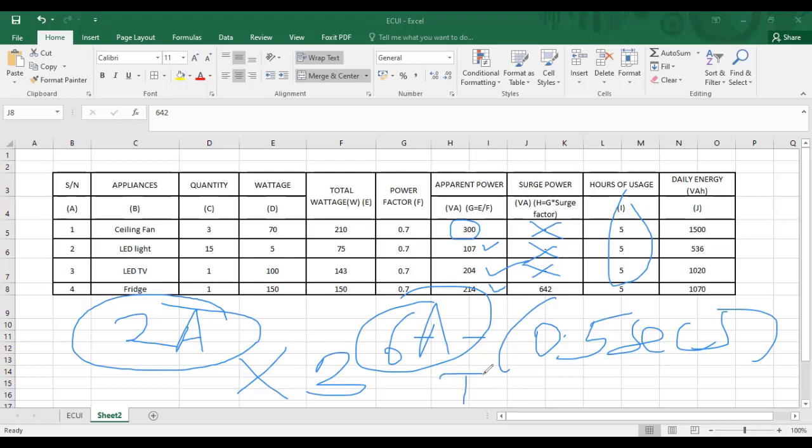So we can say, let me just say IN is the nominal current, and times 3 of the nominal current is the surge current. Let me just use X here as surge. So if the normal current is 2 amps and it's taking times 3 of it to start, that means it's taking a current times 3 of its nominal, which is 6 amps, to start.